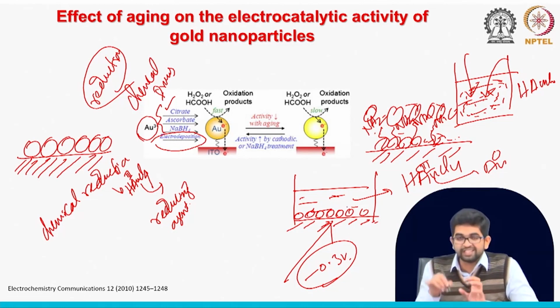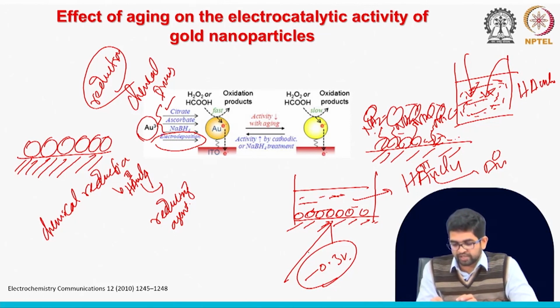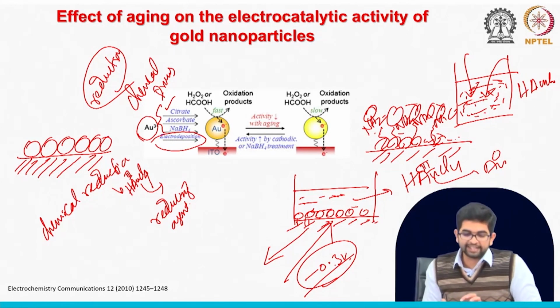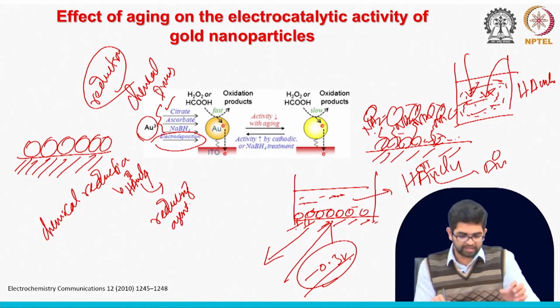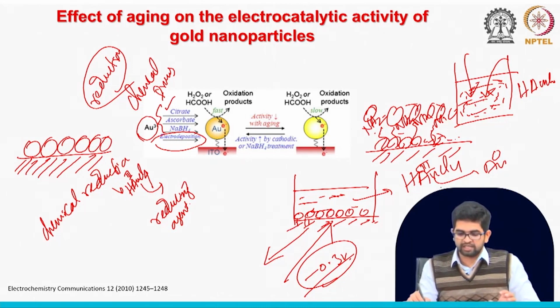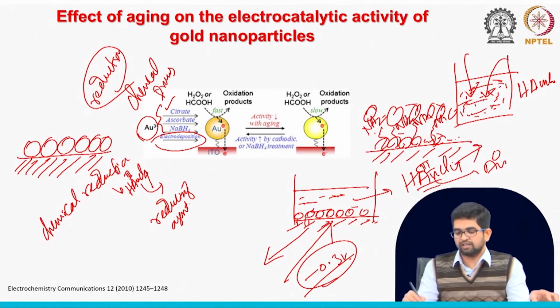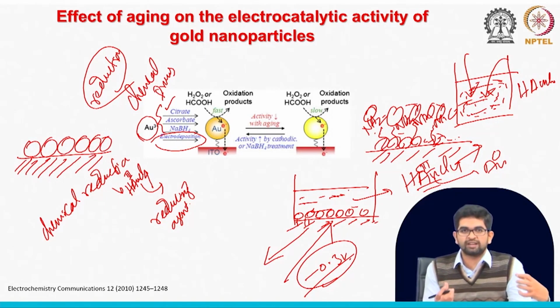So this is ex situ, and this is in situ, meaning inside the solution, when you apply some potential, this nanomaterial will be deposited. What is the driving force here? It is the negative potential. This is called the electrodeposition method. Using this method you can deposit nanoparticles. Here I just gave the example of gold. You can try some other metal salt, and those metals you will get in the form of nanomaterial or nanoparticle form.